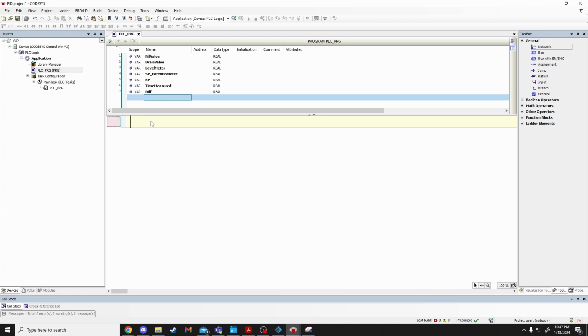This water tank is fairly tricky because it sloshes around. It's a physics simulated environment, so this water gets sloshing, and if you have oscillations in your system, it's going to just oscillate out of control. So we're going to have this be a pretty damped system. It's either going to be critically damped or over damped, one of the two. But we need to avoid those oscillations at all costs.